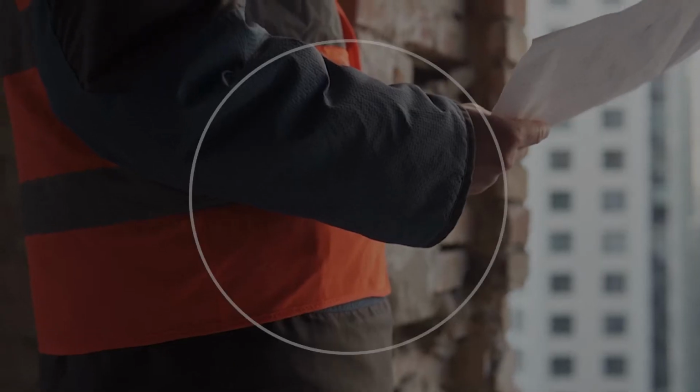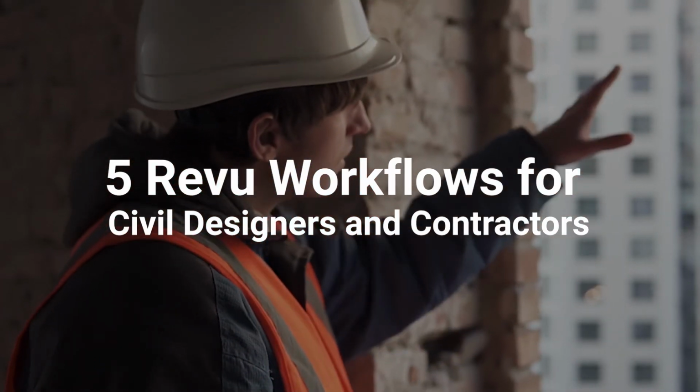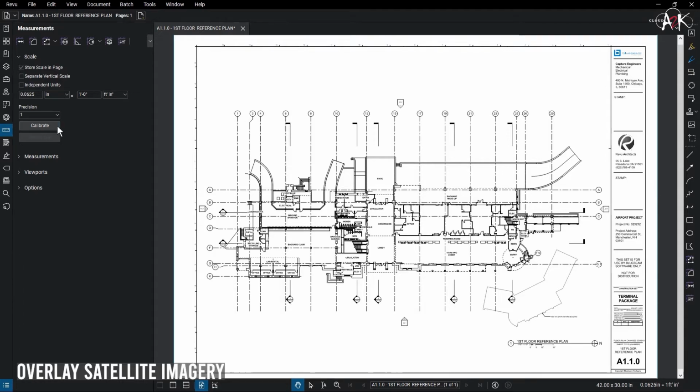Let's take a closer look at 5 Revu workflows for civil designers and contractors. Overlay satellite imagery. Whether you do a screenshot or some other method for acquiring satellite images, be sure to include the scale in the image. This will make it easier to calibrate the image.